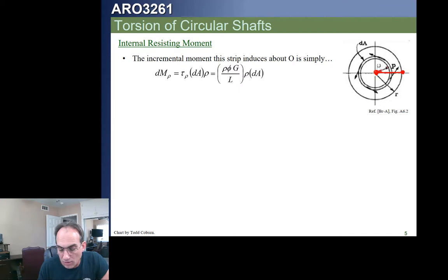If we look at some arbitrary radius rho, we can calculate the average shear stress at that point. Now, if we want the force on that little piece, let's call it the force P, it's going to be that stress times this circumference, so it's tau times 2 pi r, or pi d, times the little incremental thickness dt. That's going to be the force.